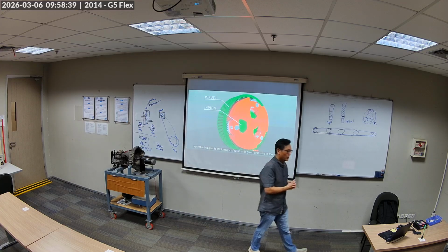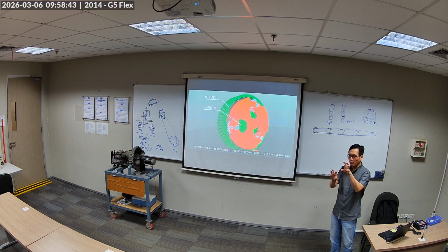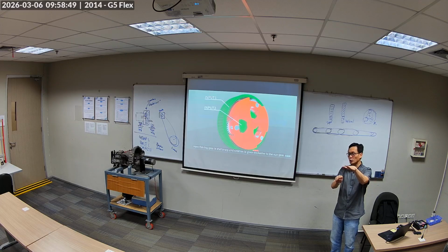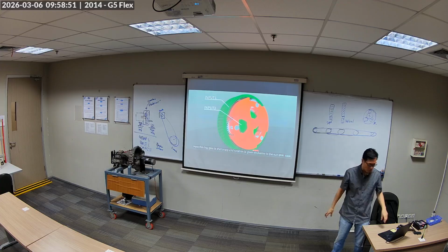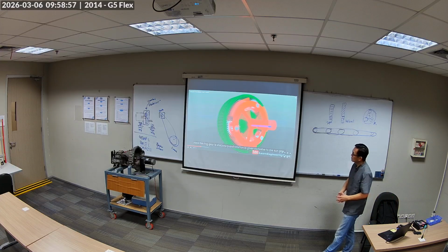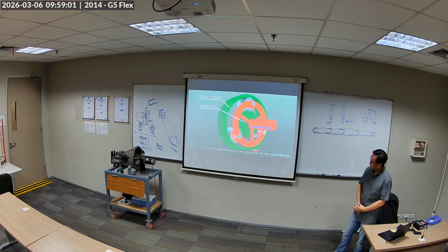Okay, that's the trick with planetary gear sets, is that you can play with the ratio by manipulating whether you fix input 2, whether you fix input 1, or let input 1 and input 2 rotate in the way you want. Here, the ring gear is stationary and rotation is given exclusively to the sun gear. This will cause the carrier to spin, as you can see here.